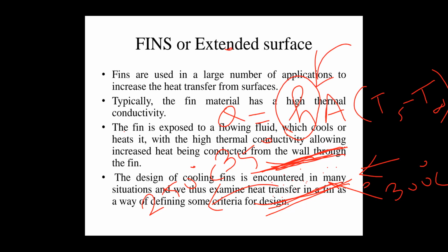But this should not be increased, it is a constant value. The temperature of the surface is the surrounding atmospheric temperature, and we cannot control it. The fluid flowing in the pipe at 300 degrees Celsius should not be changed by ourselves. So only the surface area can be changed. To increase the heat transfer, we increase the surface area, like in a fin model.